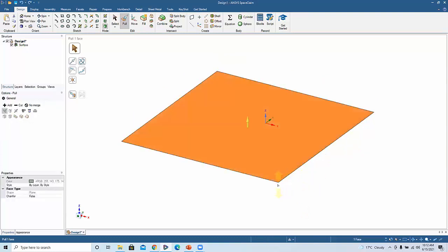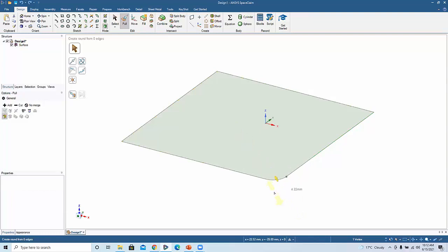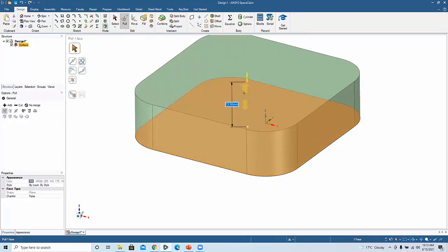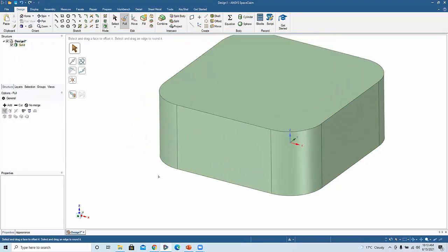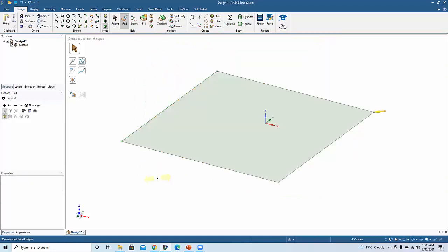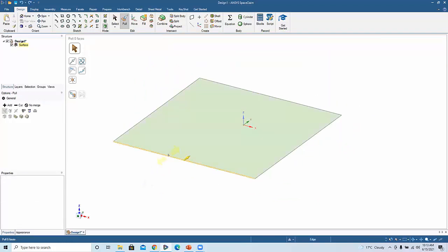It's the same thing basically when I have a model, I can actually create a round. It's the same thing when I go back and select just the corner vertex. I actually also create a round on that edge. So for example, if I wanted to create a rounded box, I could just grab these four vertices first and actually round out these four vertices, and then after that go up and create a box as opposed to applying them after.